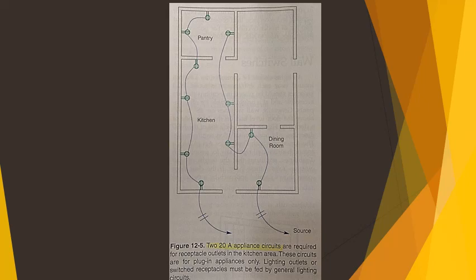Laundry. The laundry equipment will use a 20 ampere circuit that has no other receptacles. These circuits can be included with the general lighting load as stated in section 220.52(B).